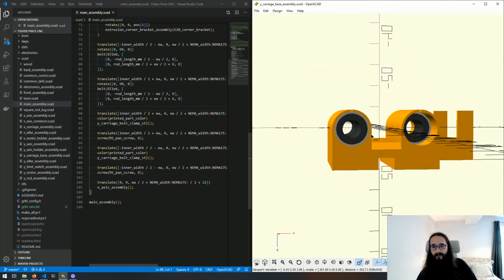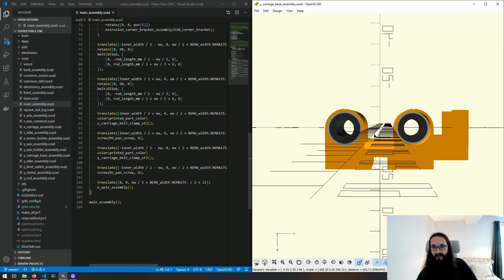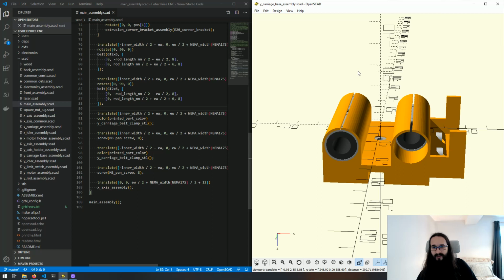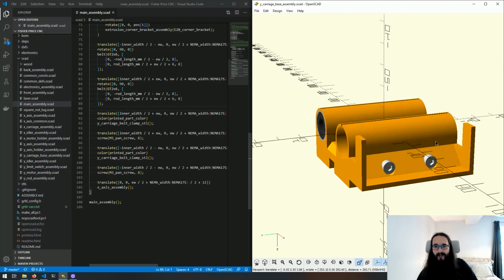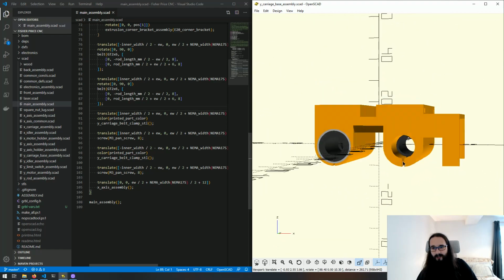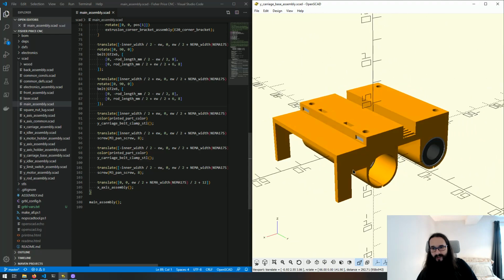Probably the slicer doing some kind of magic, but these bits end up actually expanding a little when you push the bearings in, and that gives them very good grip on the bearings. So it's a nice little flexure thing that just holds them together, and that works even in PLA.